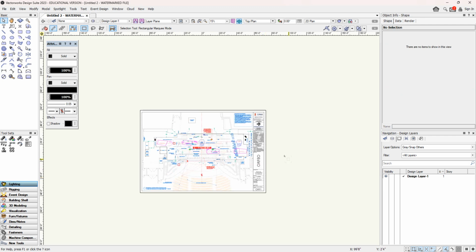So I think that's everything you need to know for both AutoCAD and Vectorworks to bring those files in, get them scaled correctly, get them on the 0, and then start taking those coordinates. Please, please, please, always, always, always, before you start taking points and writing those points down, verify the scale of the drawing, double check that with the tape measure that things are the size they're supposed to be, and then double check that 0 is where you think it is supposed to be.